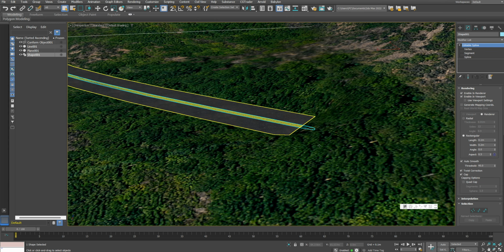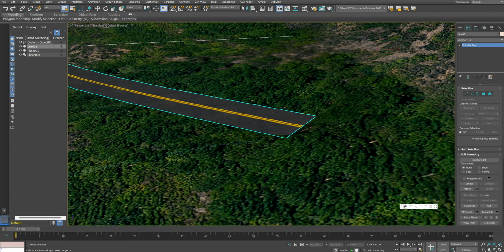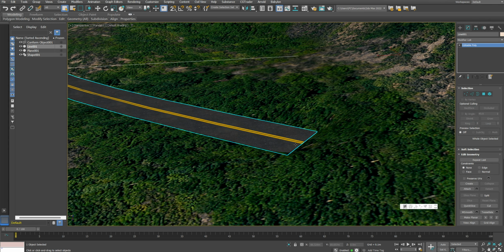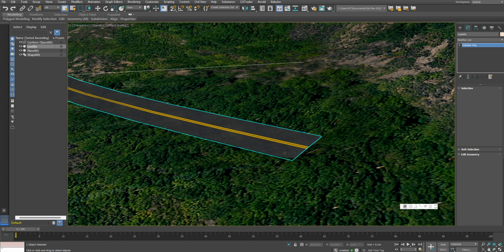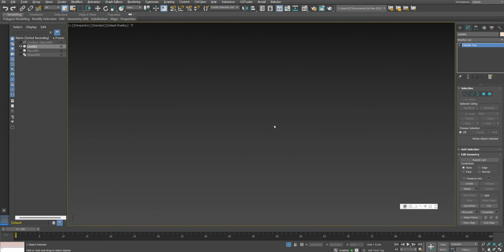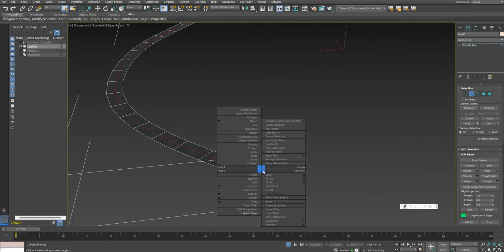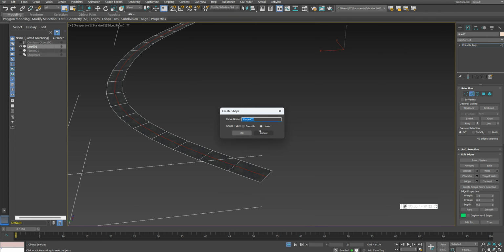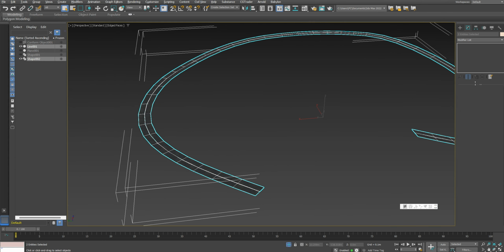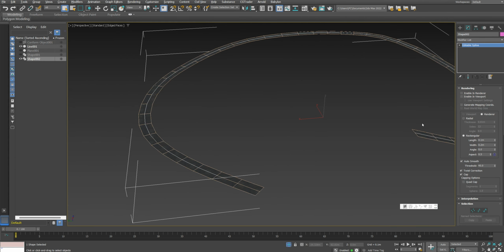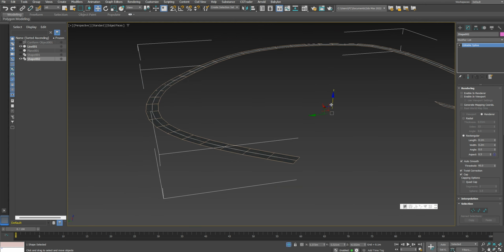Next we can give it a camera. Let it roam along a path. We can choose again this pavement. We are still choosing this line. Extract this line with the right mouse button. After we extract it we are going to check off these 2 boxes. Lift this line up 1.5 meters. Put this down. Lift 1.5 meters in the Z-axis.